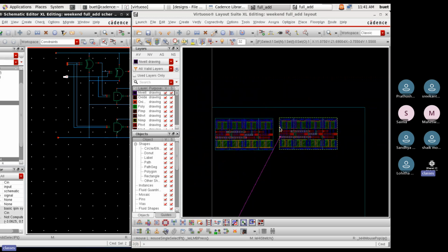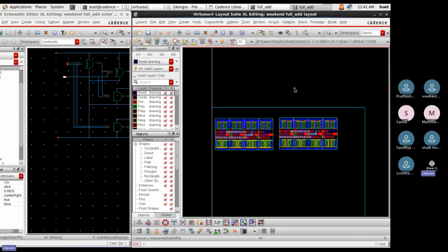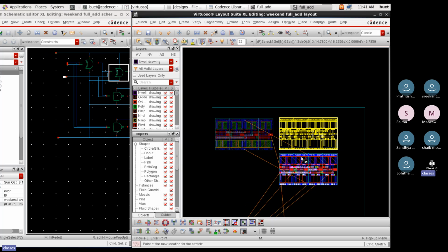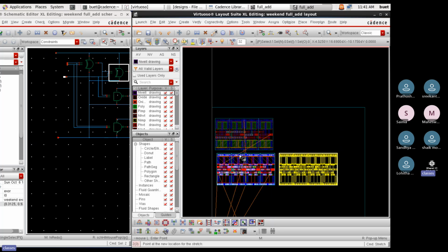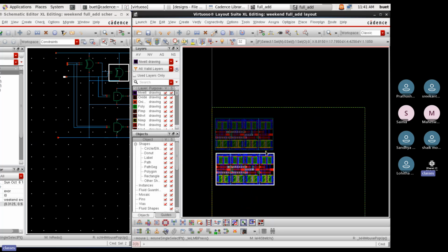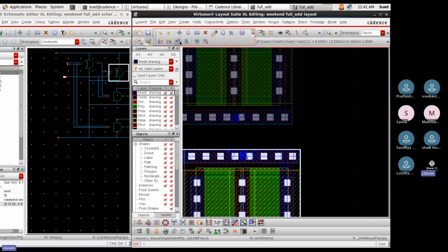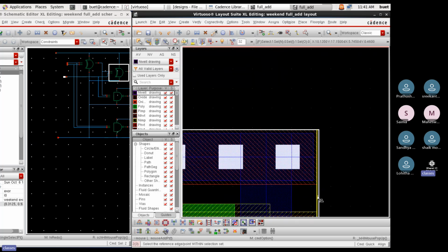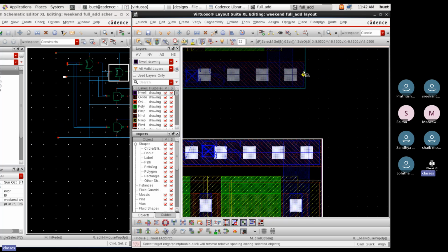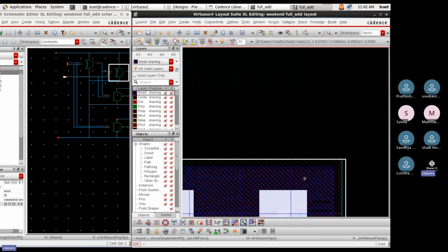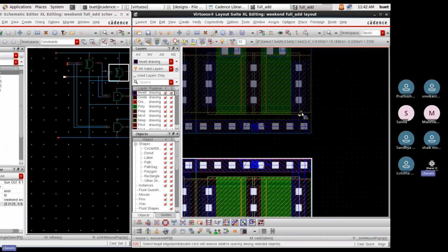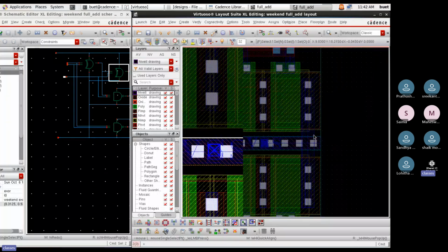Okay, let's go with that one only. Better to go that way. In this also the output will become bigger. We cannot consider that input should create one output, so both the things will get hampered here. Better we will do it with a higher metal. Not an issue. We can do that routing with a higher metal. We can put it here and then align it and put it somewhere here.